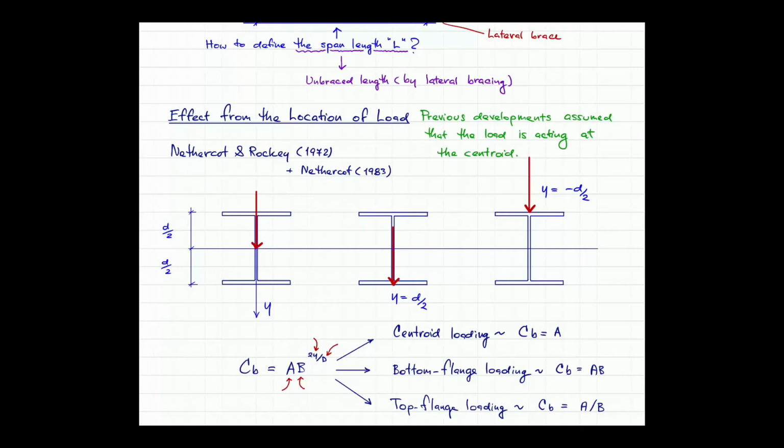The easiest one, the D. The D is the total depth. Okay, well, in the steel table they give you the H as the height of the cross section. So that's your D. A and B are to be figured out from the table that I will show you on the next page. So that is associated with the pattern of the load and the boundary conditions.